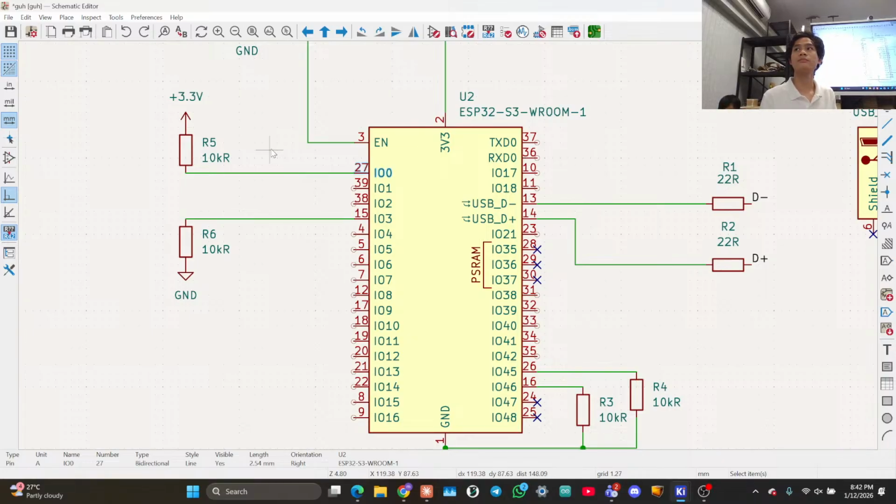So that's why we put a pull-up resistor. The value of the resistor doesn't really matter in this case. It's just to prevent it from instantly sending 3.3 volts through it and potentially breaking. You can think of it as a current limiting resistor. For example, if that pin becomes an output pin and tries to pull the pin to 0 volts, then you have a dead short to ground through the microcontroller. Essentially that's why you have a pull-up resistor, and not just a connection to 3.3 volts.